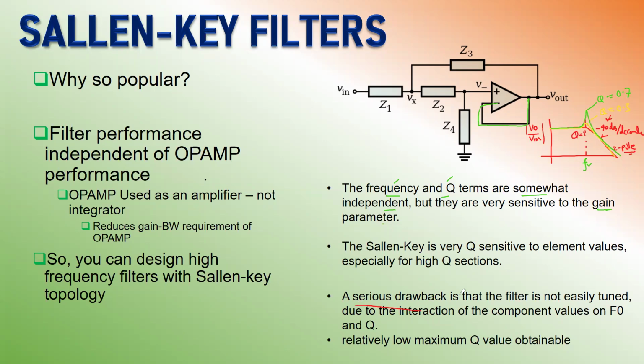But the serious drawback of this filter is that it is not easily tuned. You cannot really tune the frequency. Let's say you design it for a specific frequency and you don't find it easy to vary and tune the frequency, because there is an interaction of the component values on F naught and Q. So these component values are sensitive to two values, that is the frequency and the quality factor Q.